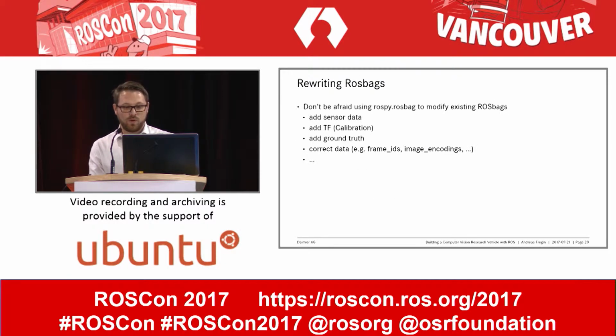We are working with recorded images a lot and therefore use ROSBags. And when recording datasets, you sometimes don't get everything correct. You may either publish a wrong image encoding, or you may decide to rename your frame IDs, or you may want to add offline computed sensor data like disparity images later, or you finish a labeling process and want to include the ground truth data inside your bag. These are all real examples, and we especially like, in this case, the rosbag Python module, which works just great for modifying and rewriting bags.